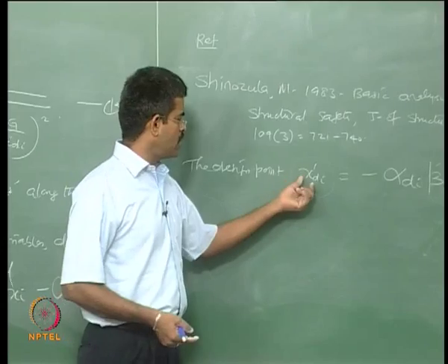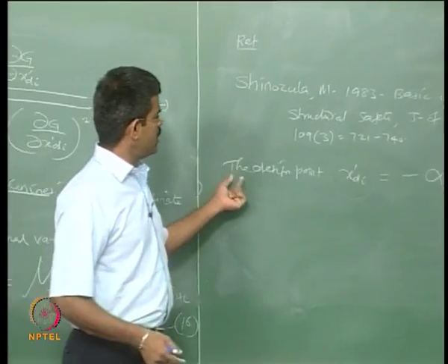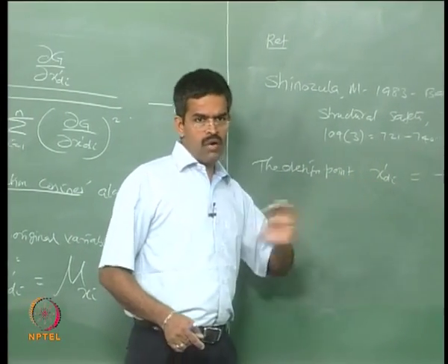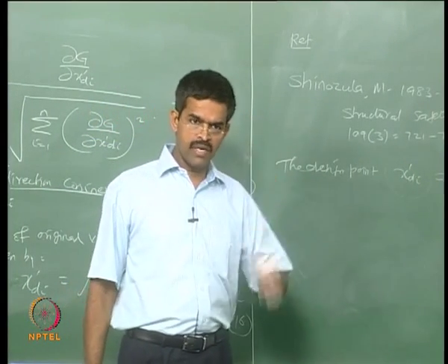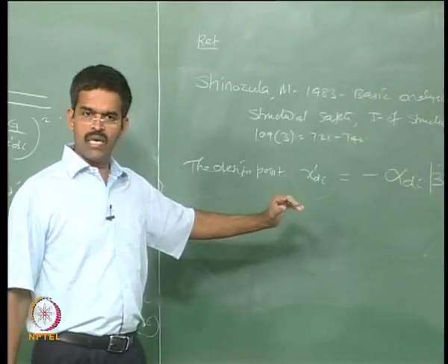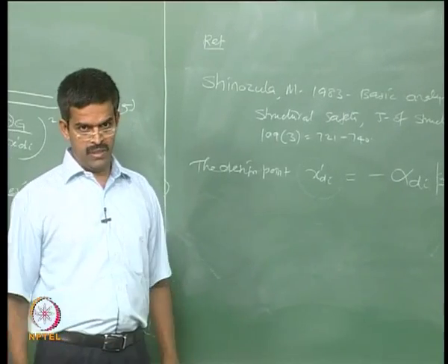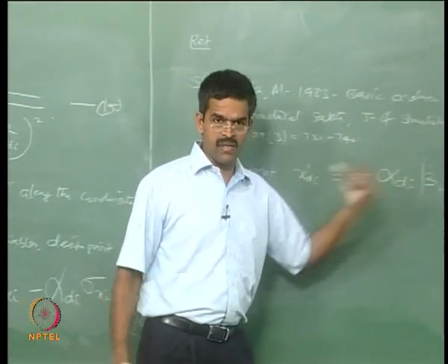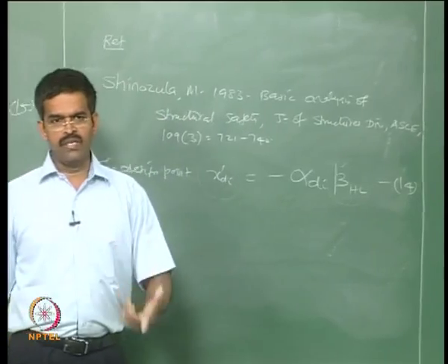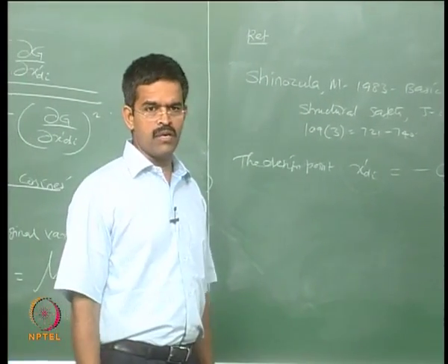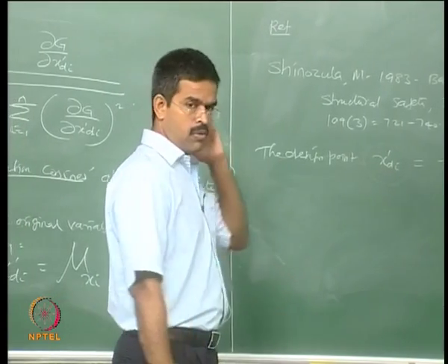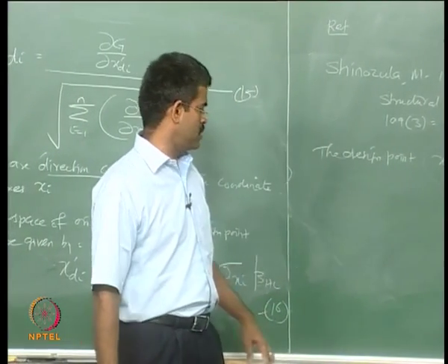So, you will ultimately get the coordinates of the design point which does not vary between the first approximation of the standard variates to the actual real random variables which are dependent on each other. The corresponding beta HL will give you the safety index of the problem. There are good illustrations and examples available in the literature. Unfortunately, in this lecture I am not able to show you some examples of worked out problems.